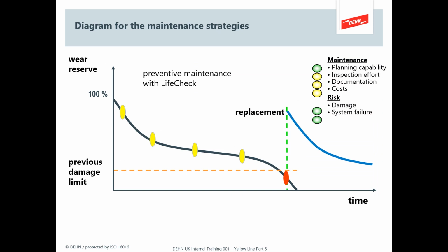Now, the normal maintenance regime with SPD is to wait for it to fail. So once the SPD has failed, I then replace the SPD, and then it's business as usual. So there is the possibility of some damage occurring, and that's a problem. So with Live Check, it gives me that much more proactive and preventative maintenance regime. So if I get an SPD which is indicating that it has suffered some stress, now I can at least get on ordering it before it fails completely.